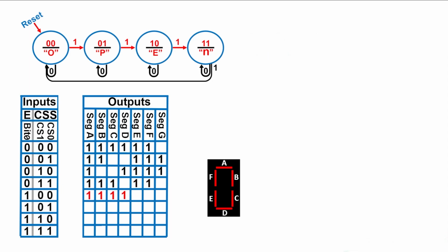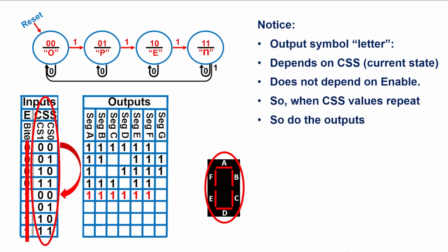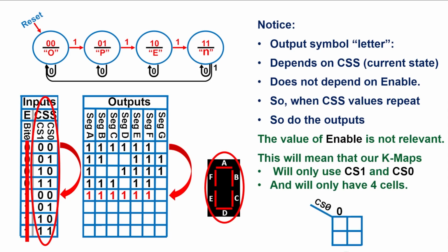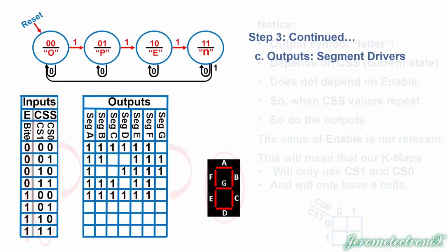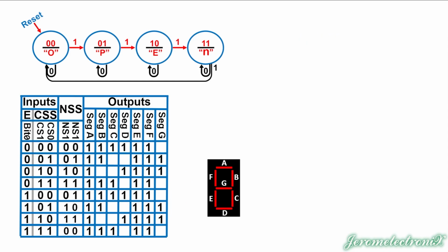And then we're just going to do it again down below, because if we get 1s, well, here I am saying we don't need the inputs at the output decoder. So all of this we're not going to need anyway, but it's just a repeat if we get 1s. So we'll only need 4, but I'm just repeating again. Probably could just eliminate these because we don't need them, but if we have a full truth table like this, the next-state logic requires 8 rows, and the outputs for the 7-segment display only need 4 rows.